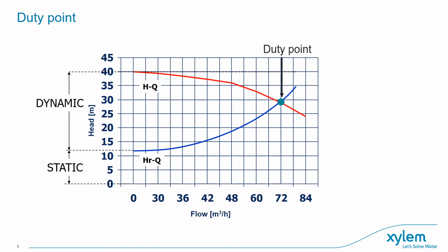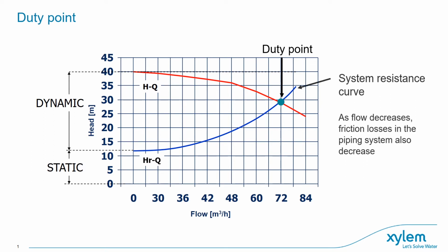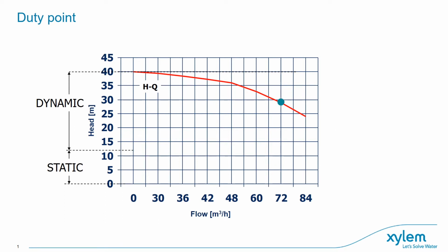So this then produces a system curve, and as you can see, as the flow increases, the pressure increases on the system curve to overcome the increased friction loss that we have in the piping system. And then obviously in reverse, as the flow decreases, we can reduce the pressure because we have less friction loss through the pipework system, which the pumps have to cope with.